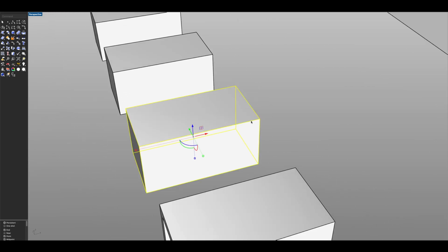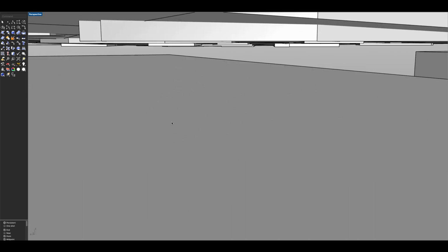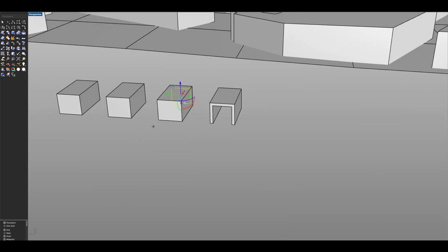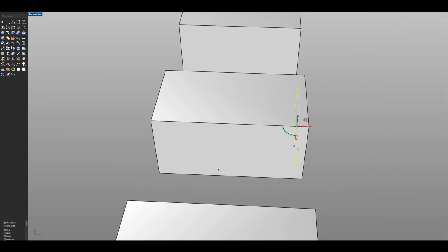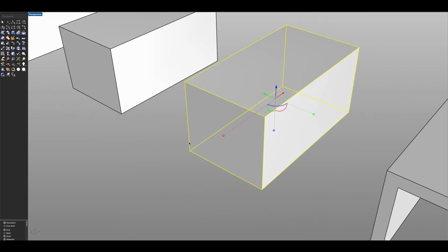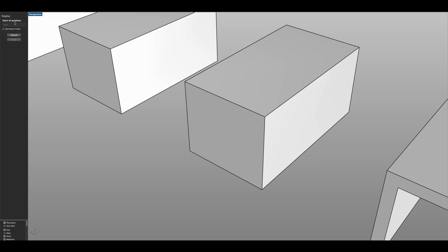And now we want to select our line again, and let's mirror it to the other side of our block. So mirror, then like that. Okay. On this side, let's go for 1, 2, 3, 4, 5. And here let's make an offset of about 1.5 like that.